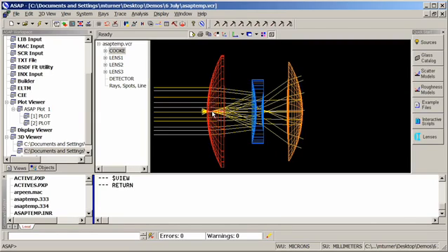But if I'm using this to image a high-power laser, for example, even though the amount of energy in the Fresnel reflections is minimal, if this is a high-power source, I could be concentrating enough energy to cause thermal issues, either heating or even fracturing of this component. This is something that an ASAP analysis will allow me to see before the system is actually manufactured, and now, if necessary, I can go in and modify my design to eliminate this shortcoming.